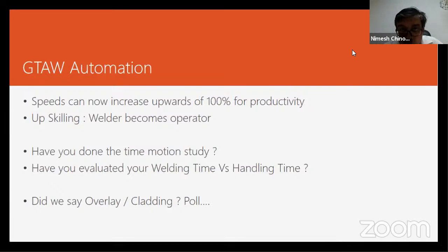We are facing issues of the distortion and bulging of sheets up to 3 mm. MS, aluminum, SS, there is a distortion in manual TIG. So you could reduce the distortion by using pulse TIG, by using a cold wire feeder. It will reduce your heat input, and also by increasing your welding speed. If you move into automation, it will be much faster. If you have any particular product in mind, Mr. Jamin, we could discuss it offline, or you could send an email to us and I'll take it from there.